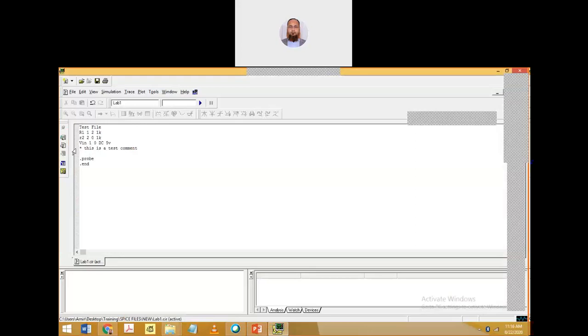Let me complete our program. What we have done here is we have written the voltage source. The only thing left is the DC analysis. I'm deliberately using .dc in capital; we can write small as well, no problem. I told you this many times. So this .dc tells us that DC analysis is going to be performed.